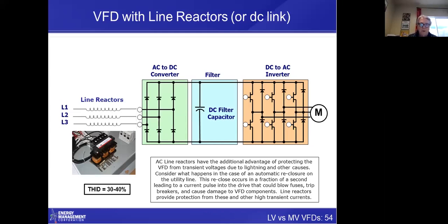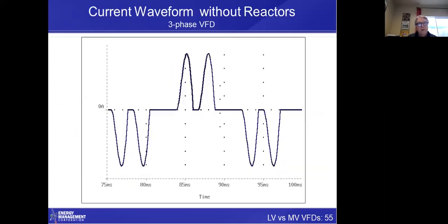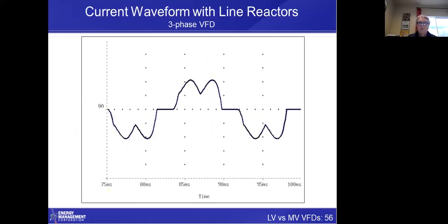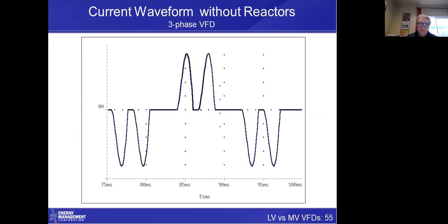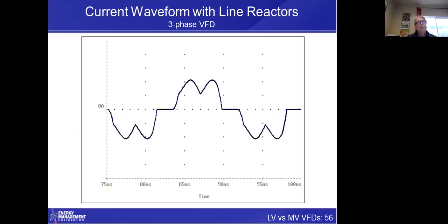They're cheap, they're easy, they can be used on any variable frequency drive. And I'm always preaching that. Here is without reactors. Here's the waveform with reactors. Now, I'm not saying that's a sine wave. It's not like it's great, but this is 100% distortion. This is about 30% distortion.